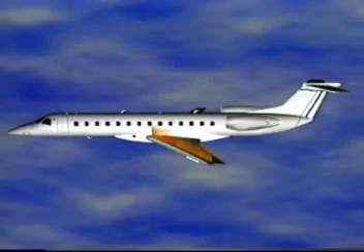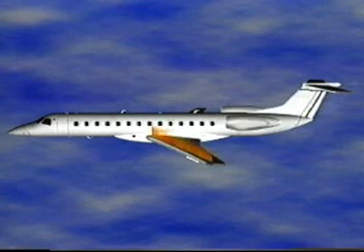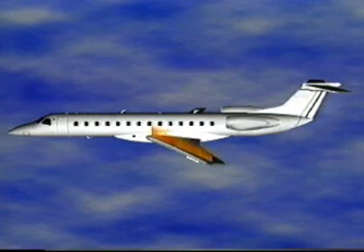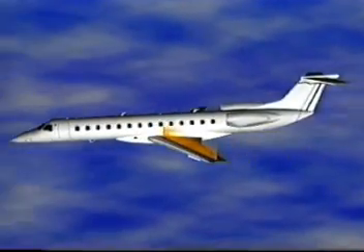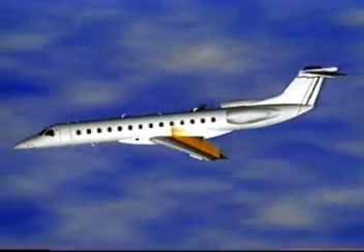Mach tuck. Observe the pressure distribution along the chord of a typical airfoil shown here in a subsonic speed and during shockwave formation. As the figure shows, the lift forces during shockwave formation act at a point nearer the trailing edge in relation to the subsonic flow, where the lift is predominant near the leading edge. If airspeed is further increased, shock waves move closer to the trailing edge.